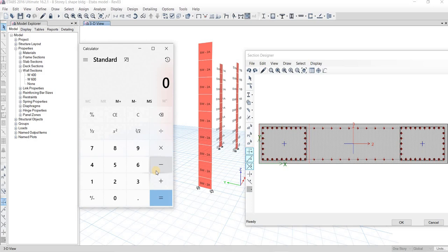So let's say we have 32 mm, we will use 32 mm instead of 25. So the 32 mm is, I think, 615. So pi d squared over 4 using 32 mm, that is 615. So 615 times 30 equivalent to 18,000 divided by 600 divided by 800, that is 3.8%.